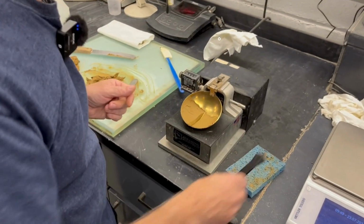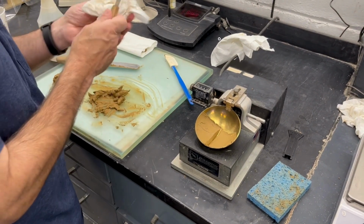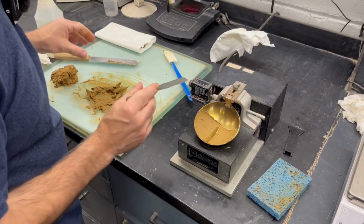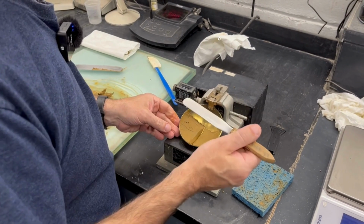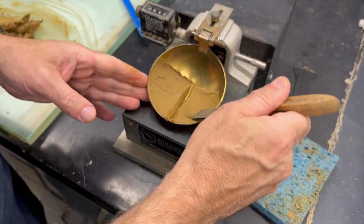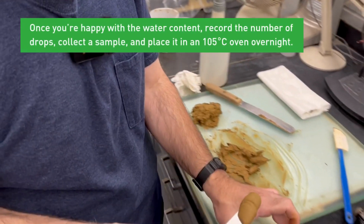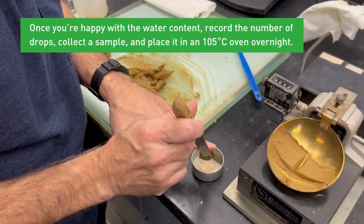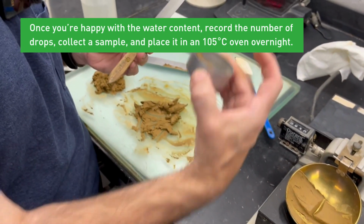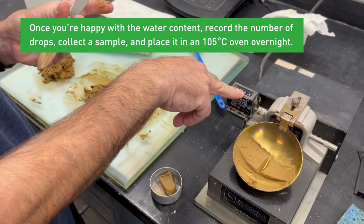I like that. So now that we're close, we're going to grab the spatula. We'll use the metal one. We're going to see what moisture content it is. I'm going to take a sample out, usually right where it crossed over, and put some in a tared cup. Then I will get a weight on that, and the cup's numbered. Put that in the oven. I will record that, and I will record how many drops it took.